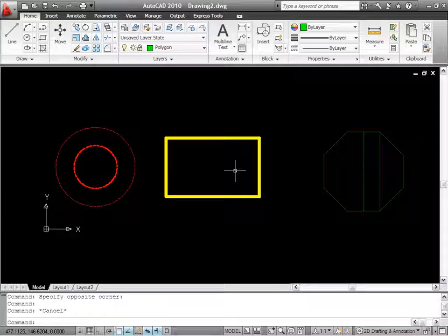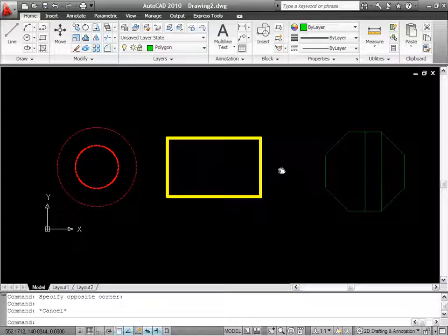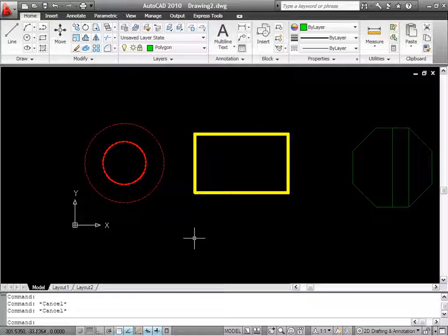So with the understanding of the layers, we would move on to take a look at the properties. To activate the command or call out the properties panels, you can just type PRO for properties, the first few letters of the word, and spacebar to continue.